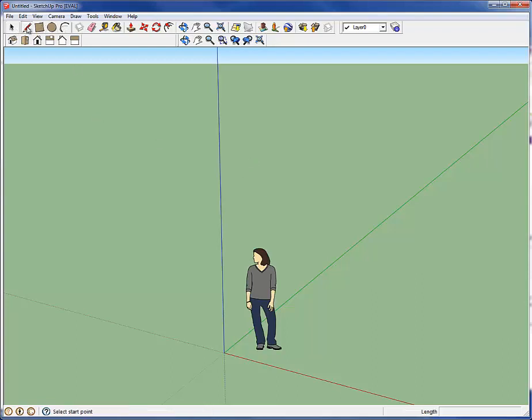The one other thing in here, just before we get started, as you start to draw geometry, if we go over here, and I'm just going to use this. There's no stacking geometry in here, so if you draw a line and then draw a line immediately over it that occupies the same geometric space, that is automatically going to be deleted, and it's going to create a division in here so that you guys can start to make and modify those geometries. Okay, you can see how it broke here.